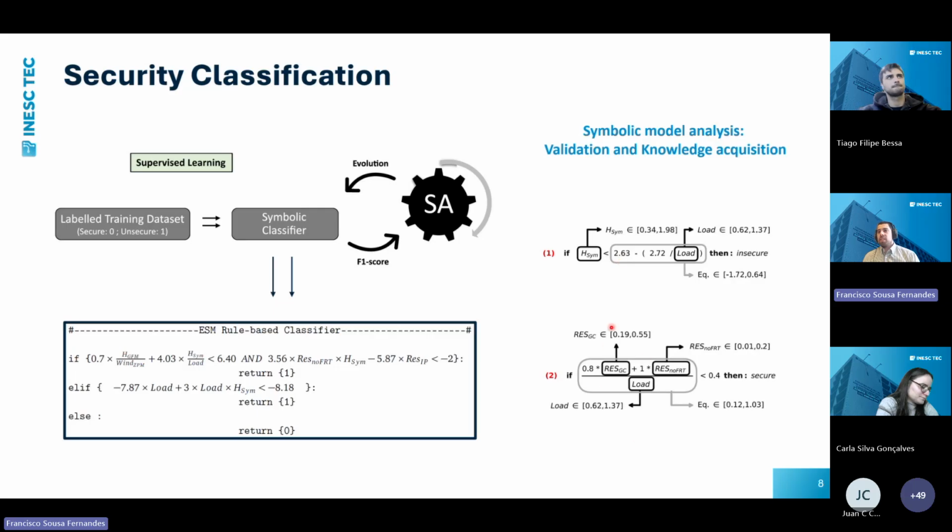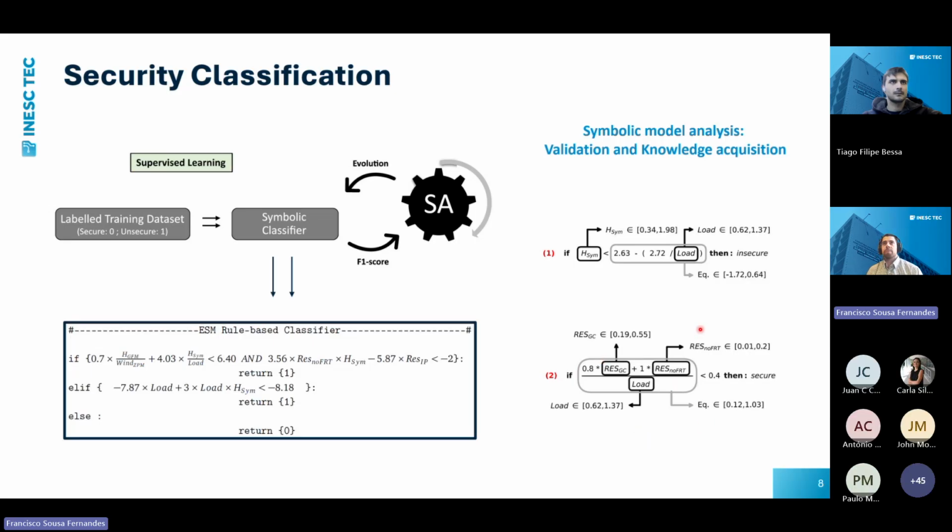And here it's interesting because on these rules that you can see right here, that result from using the model in a test bed system corresponding to the Madeira Island power system, you can see that one of the expressions that we got actually introduces basically a penetration limit that conjugates the maximum amount of renewable energy that follows grid code and the one that doesn't in relation to the load. And this was automatically generated, and it makes total sense based on the physics of the system.